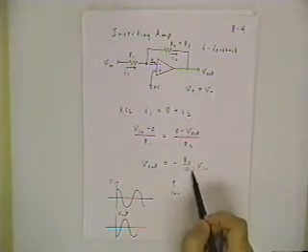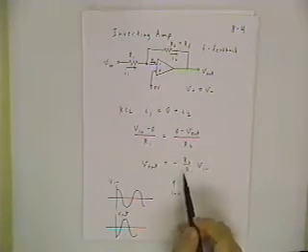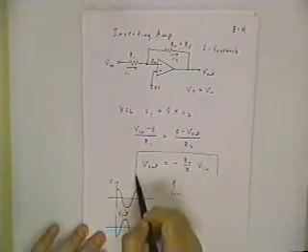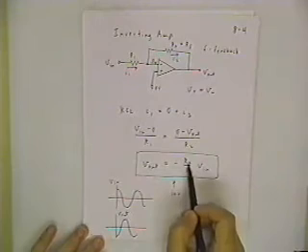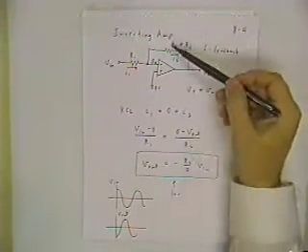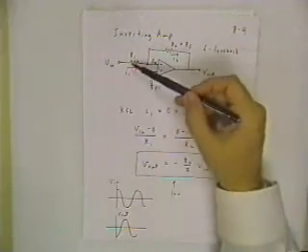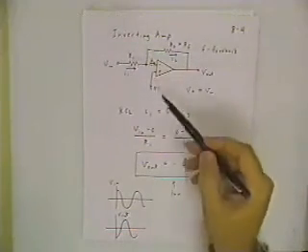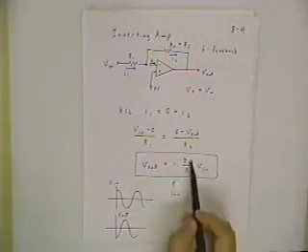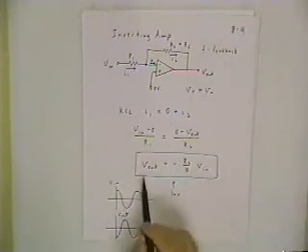But you can make this ratio whatever you want. That's probably, as I said, the most important thing for you to remember about the op amp circuit, because what we can also do is substitute impedances for resistances, and we can have RLC combinations here, RLC combinations here, and to figure out the output versus input, you just make these phasors, and make these impedances and use the same basic layout.